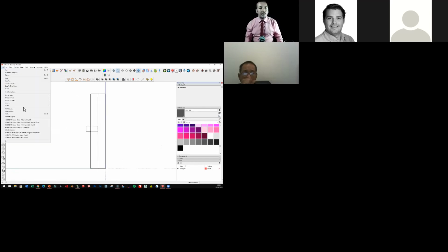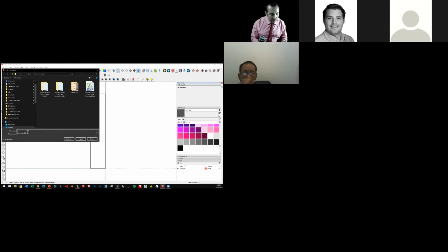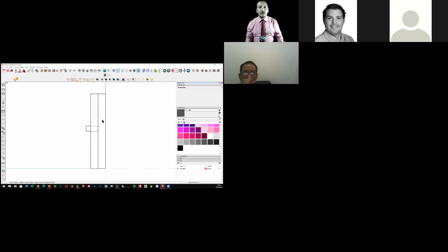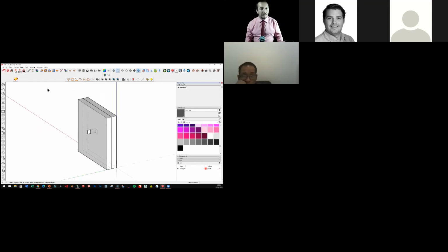Now I'm just going to export for our first part a 2D graphic as an AutoCAD DXF. And I'm going to put this in as example 2, 1 straight wall. What I'm going to do with this is ensure that my U value that I use for my 3D is exactly the same as it should be in the 2D flanking element.